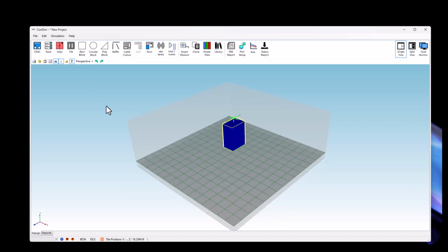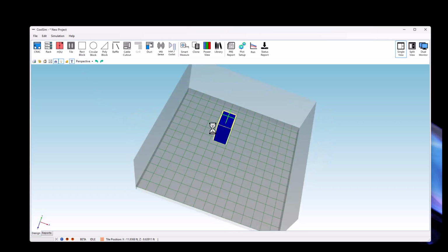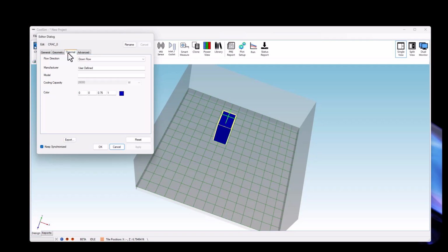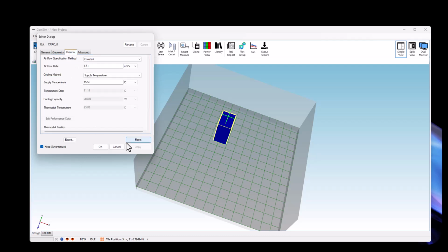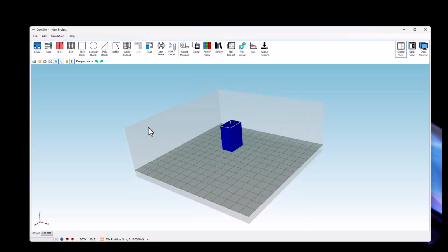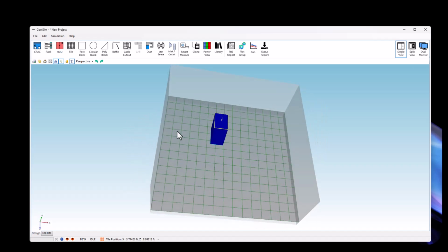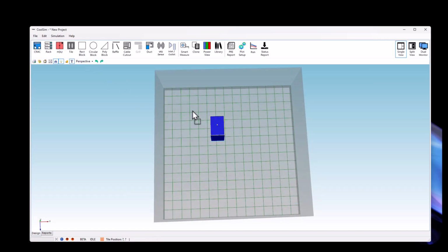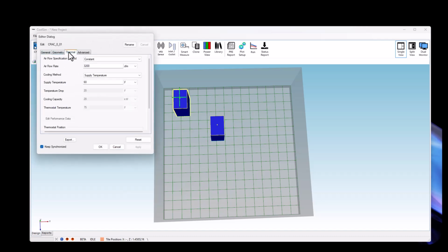So now what will happen is, of course, all your units will come up in the properties that you're interested in operating in. Sometimes it takes a close and a restart to get that to happen. You can notice that one was in metric. Let's just drag in another one. So sometimes you do need to restart CoolSim to get these to take effect. Oh, no, you just have to drag in a new object. You can see there the old object was reporting in SI. The new object I dragged in is reporting in CFM. So it doesn't look like you need to restart.